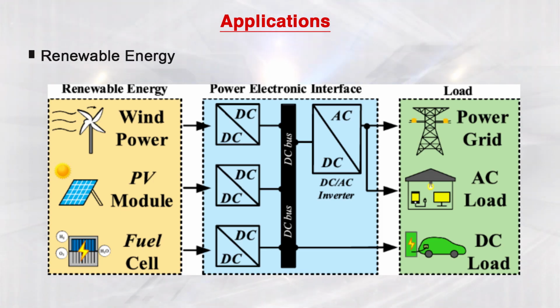We take the input voltage and input current from the PV module or from the wind based plant, and then these input voltage and current, the PV voltage and current, are supplied to the MPPT control. It could be incremental conductance based control or some perturb and observe based control, which generates the duty cycle at a certain switching frequency to control these DC-DC converters.